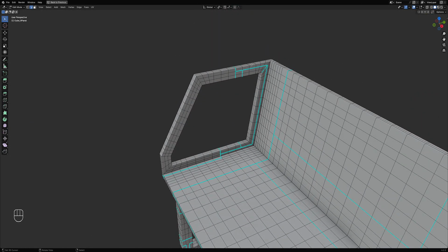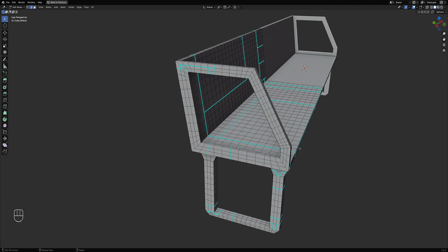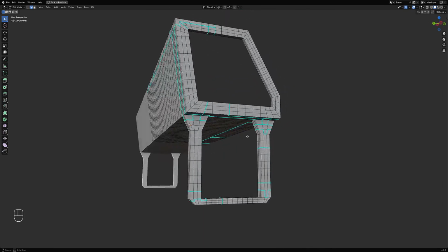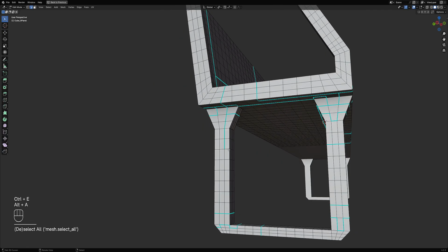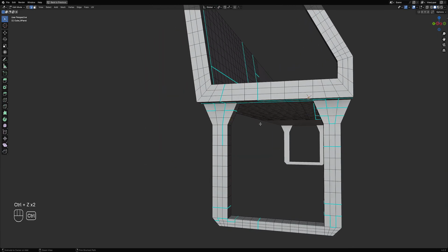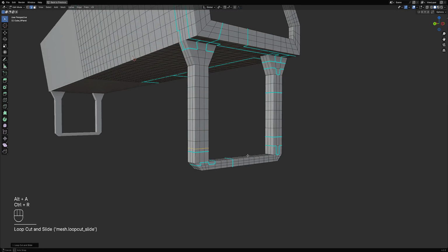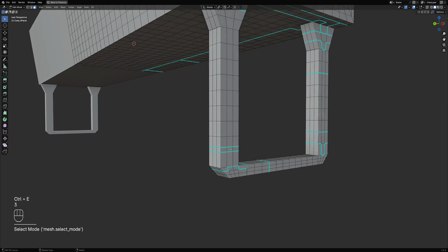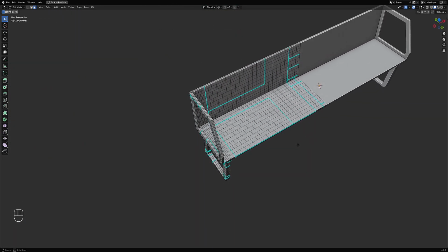Just make sure that the mark sharp edges are contiguous, meaning that they form a boundary or encircle faces or the panel islands and not end abruptly like this. So not that. You have to make it contiguous, meaning that it's interconnected to the other face elements. So you can create effects like this, mark sharp, and then sharp. So they are all contiguous.